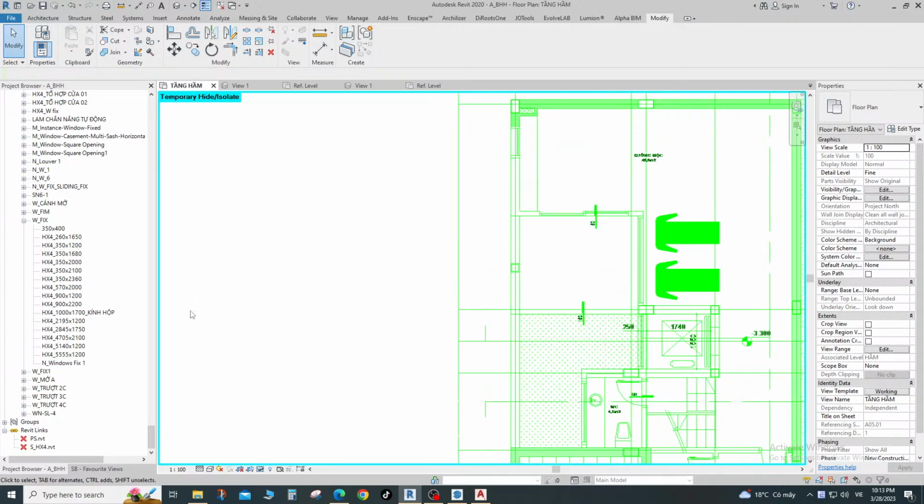So okay, then you need to choose. Oh, hang on. I'm going to use the Australian standard one. Okay, structure column, column, steel, Australian standard UB, and then pick a size. So I guess maybe 500, 455. I'll pick this one for example. And then to place the column, it's very simple.